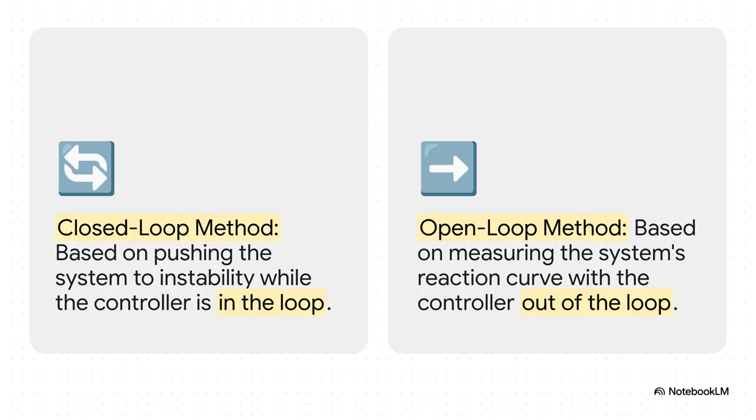This one's much safer. You take the controller offline and just give the system a little kick, a step input, and you watch how it naturally reacts on its own.